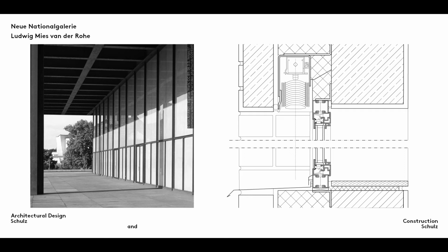The emergence of iron and steel in the 19th century saw the advent of metal window frames. Their high rigidity makes it possible to produce slim profiles and so an elegant look. The difficulty with these metal frames is the high heat conductivity of steel, which can result in significant transmission losses and the formation of condensation. Constructing steel window frames with a thermal break is an expensive business.